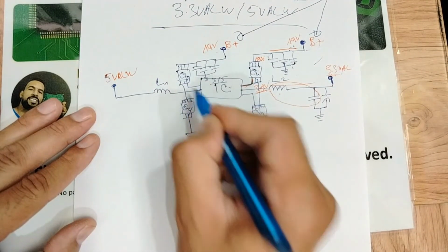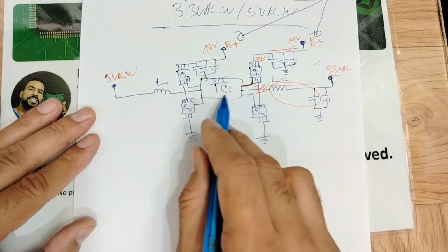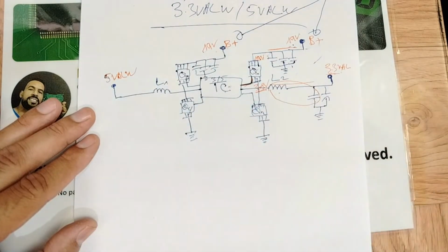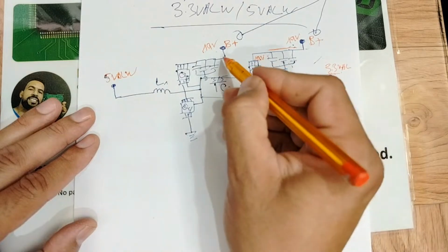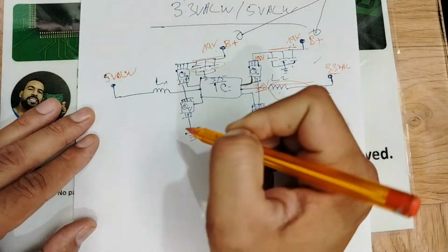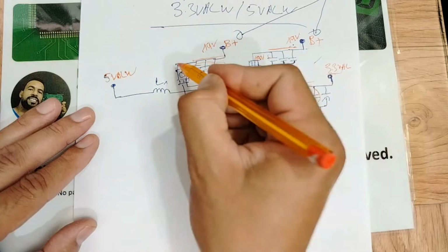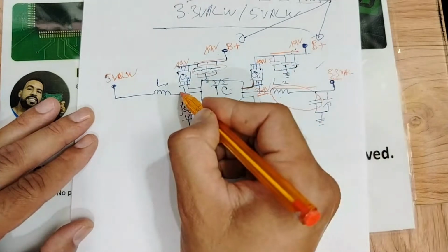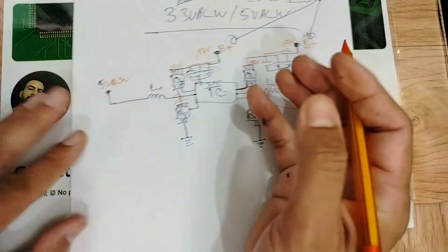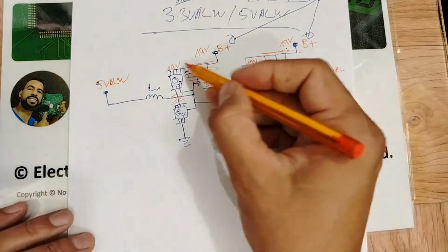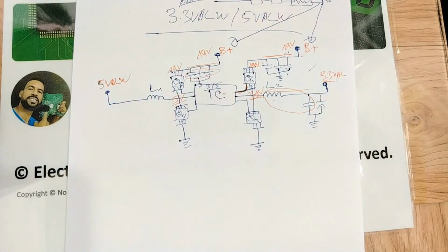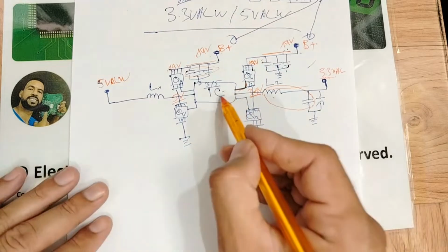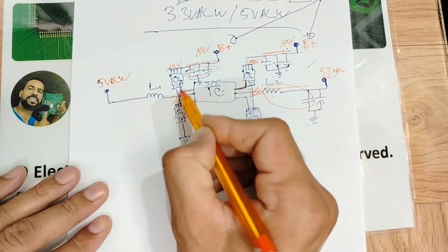The two MOSFETs also are controlled by the charge IC. So the same 19 volt, my friends, will pass through these ceramic capacitors to be filtered, and then will be present here, applied to this MOSFET. We will get here 5 volt. Why? Here we have 19 volt, here we get 5 volt. Why? How does this happen? Because of the IC, because of this control signal.